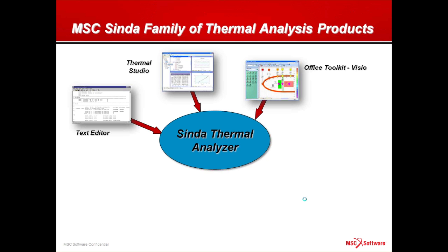And Sinda is a network thermal analyzer. Thermal models are built with thermal masses and thermal conductors modeling heat flow as conduction, convection, and radiation, or advection or fluid flow. M-dot sort of fluid flow in pipes or between PC boards or natural convection. So we can model the various types of heat transfer using the Sinda conductors.